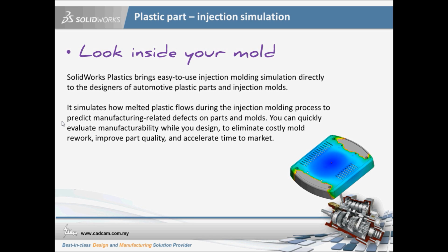Imagine if the changes are done before the mold is produced, and you can already predict all the manufacturing defects and perform design changes, then the cost of a mold change is tremendously low. Now, in another scenario, let's say the mold is there, and only from the mold testing you realize the design needs to change, then you have to spend more time and more cost on doing the redesign or mold rework, right? I hope you agree with me on this point.